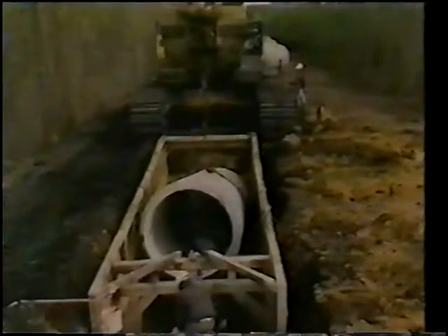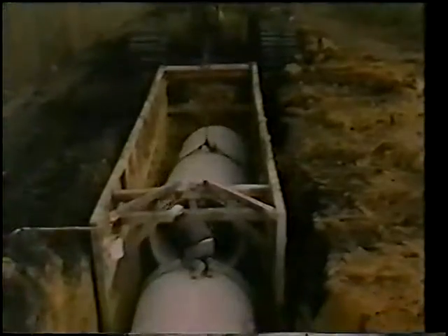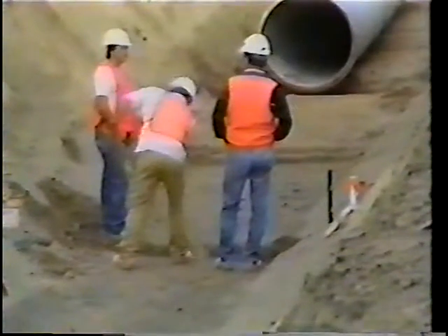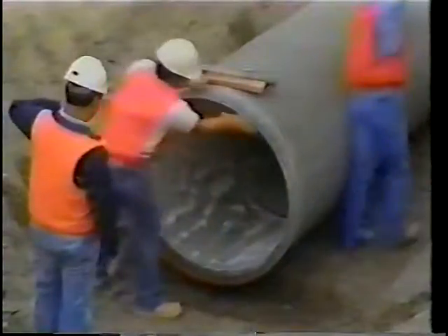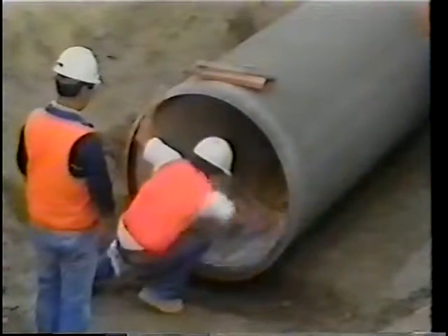Most waterline projects require a laying plan showing the direction and location of all pipe components. If the direction of working is uphill, gravity will help with joining the pipe and drainage will be facilitated. Where the bell of a joint is larger than the pipe, a bell hole is recommended to accommodate the joint so that a stress point is not created.